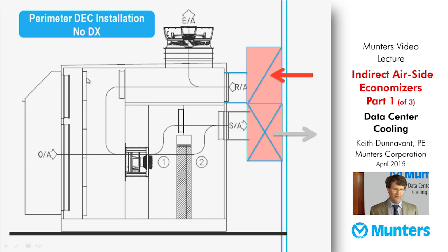You'll notice that we're only filtering the outdoor air to a MERV 13 level. Usually we'll put MERV 8 filters in the hood so that the outdoor air is first pre-filtered, and then it has a post-filter to the MERV 13 level. By only filtering the outside air, we're not adding any additional pressure penalty to the recirculation component, which helps save some energy.